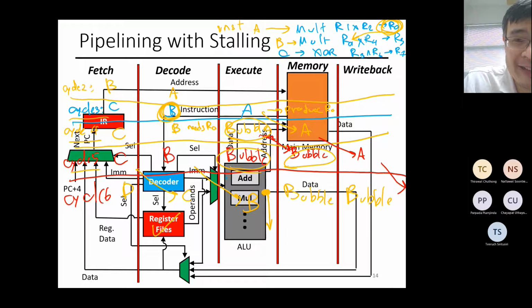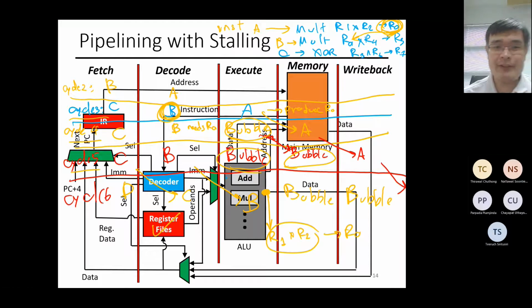That is basically R1 multiplied by R2, and that's my R0. It's the same R0 right here. I can take whatever is generated from that wire, from that output. That's the correct value that I want to write. Cycle 5 is the safe method. If I want to be more aggressive, the register file here still has the old version, but the signal right here has the correct value.